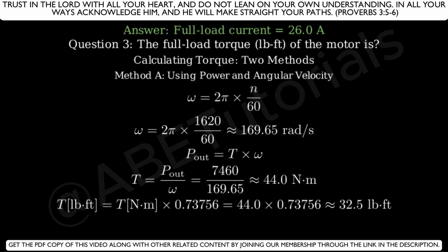Let's visualize what torque means physically. Torque is a measure of the rotational force that the motor can provide. In our case, the motor produces a rotational force of approximately 32.4 pound-feet at full load. So, the full load torque of our motor is 32.4 pound-feet.